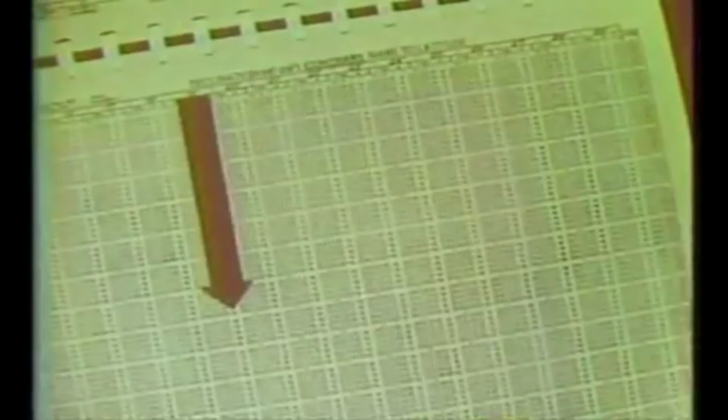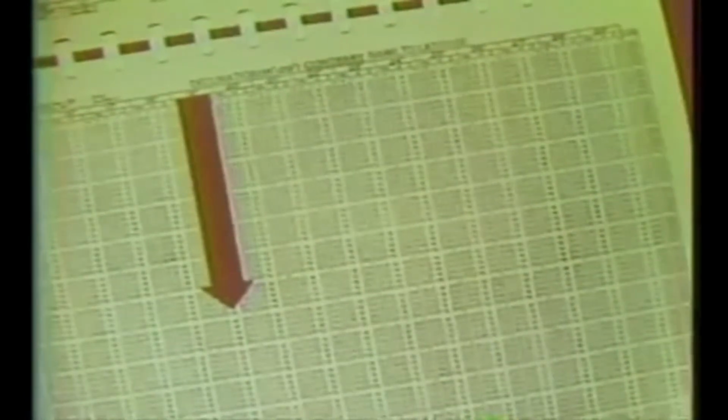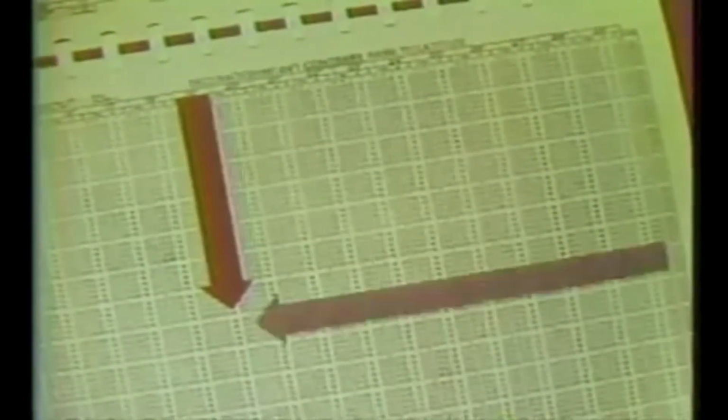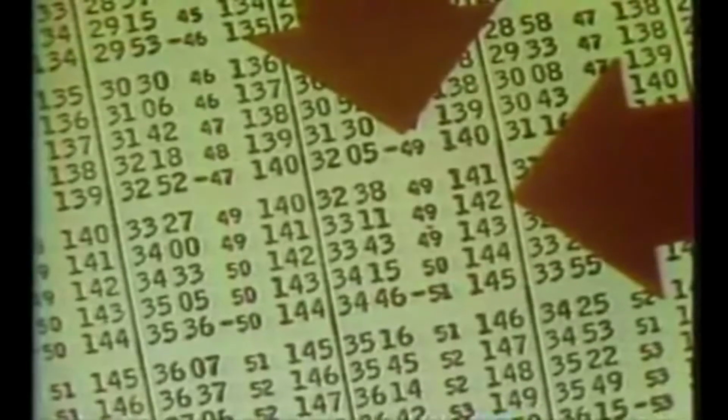Enter HO 249 with latitude of your AP, the declination of the observed celestial body, and the LHA of the body. This enables you to find HC, the computed altitude of the celestial body, Z, the azimuth or bearing angle, and ZN, the true azimuth.